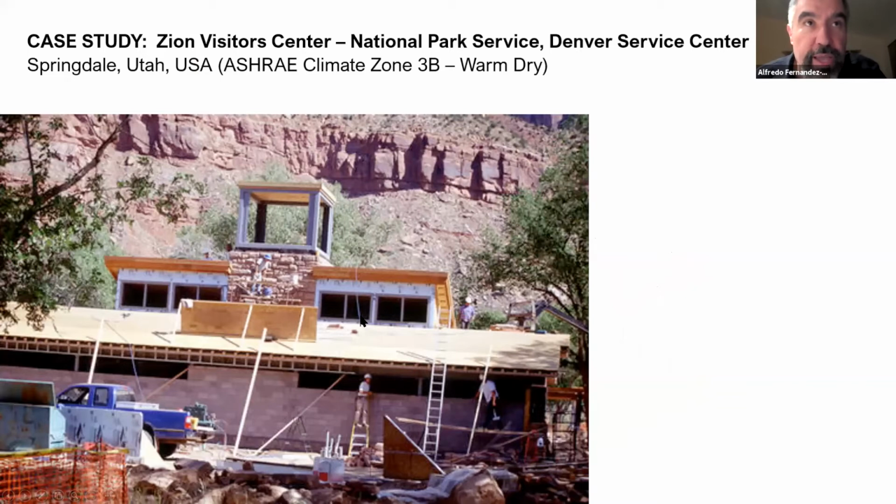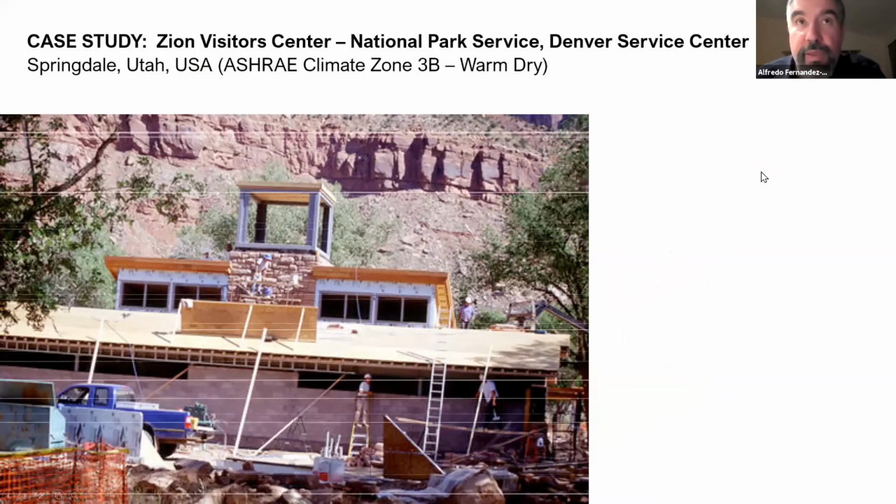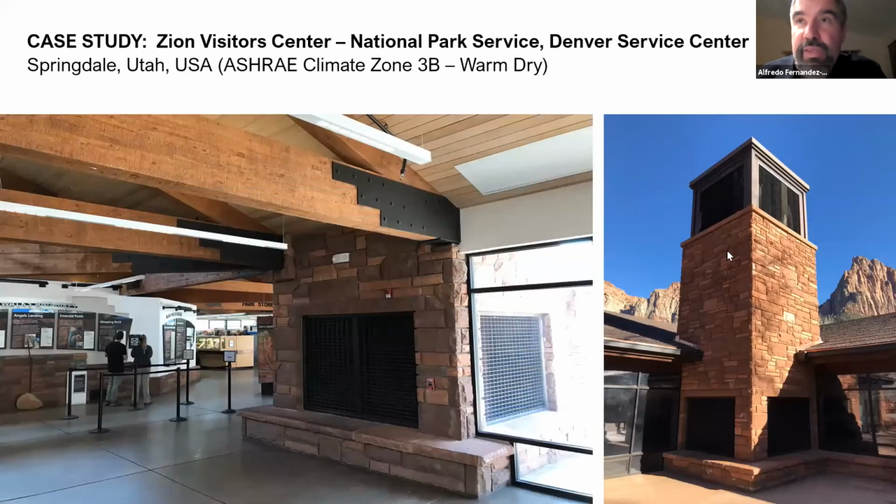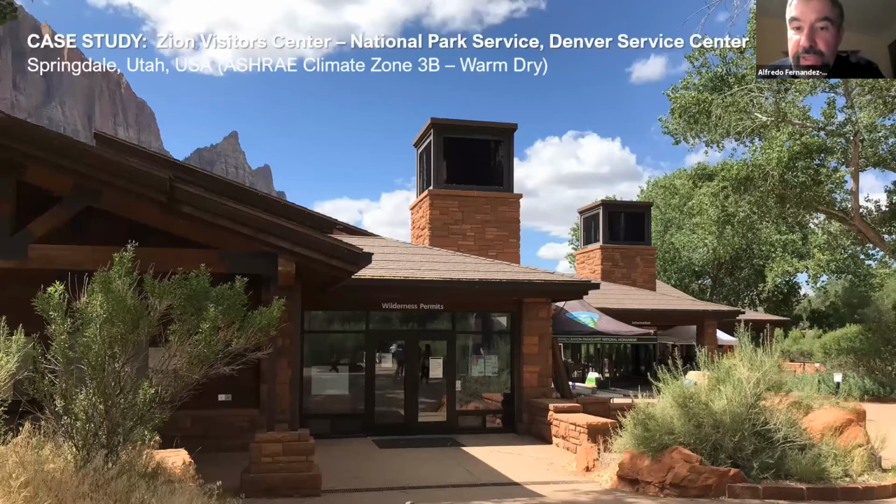You can see the Trombe wall, the high clerestory windows, and the cool tower. And that's the building as it stands today. And you can see the cool towers that are used to provide both the ventilation and passive cooling of the spaces. Visitors find the cool towers fascinating and give them the type of attention often given to a large fireplace in public areas. Cool towers work really well in this project, except in the enclosed offices, so additional small fans were included. But in general terms, in open spaces, they do a really good job at cooling the building.